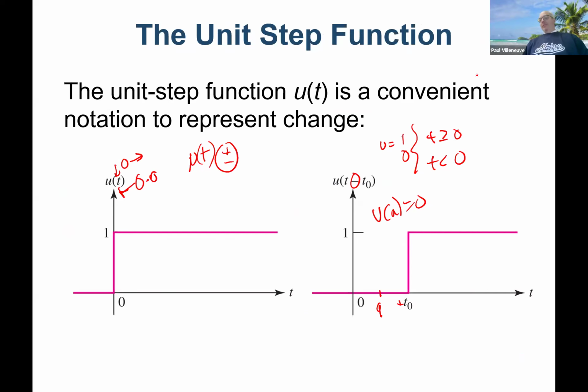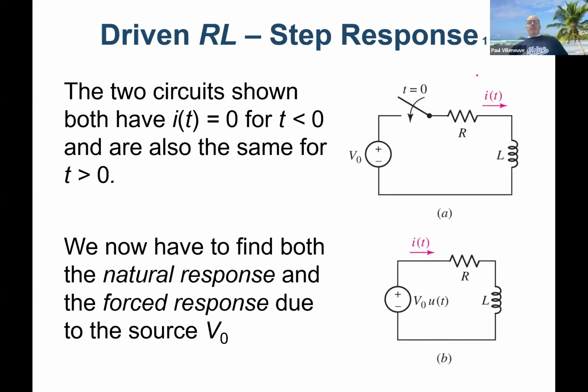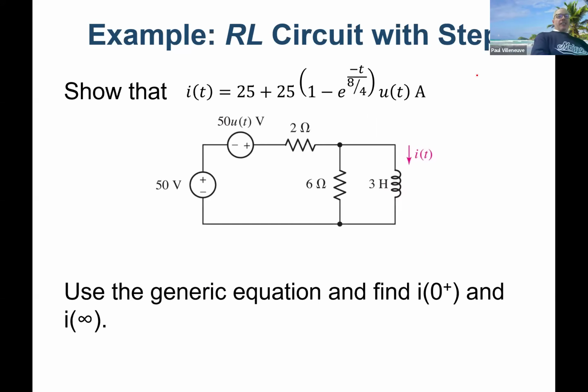Zero. So while we walk up to the circuit and we don't know how long it's been energized, this power supply is not putting out anything. That's before time t equals 0. And what happens to an inductor in steady state? It shorts out itself. What happens to that 6 ohm resistor?